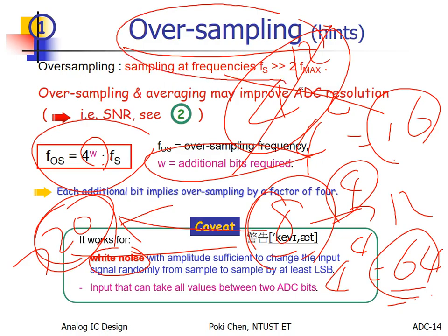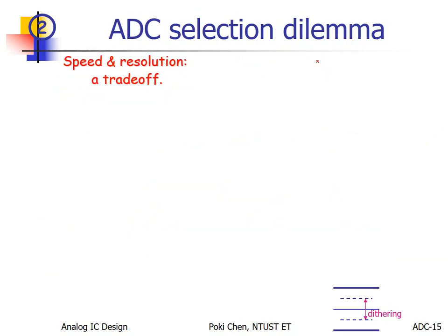Without oversampling, you have no way to implement noise shaping. So they go hand in hand. But we would like to reduce oversampling and increase noise shaping. That's it. Got it? Oversampling is not effective. If you use it to increase your effective number of bits, it is actually a pretty poor way. So we use noise shaping, the sigma delta approach. But sigma delta must be applied on top of oversampling, which is an ugly fact. So you need to apply both.